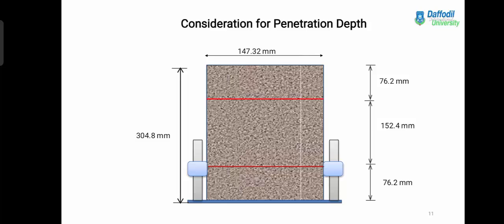After sample preparation, the dynamic cone penetration tests were performed to gauge density, obtained from the number of blows required to penetrate. A depth of 152.4 mm was penetrated, and the top 76.2 mm was ignored because of lack of confinement. Next, a 152.4 mm depth was considered for penetration depth, which is enough to represent the field condition.